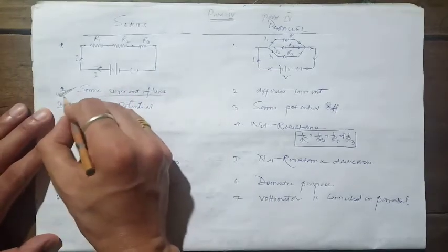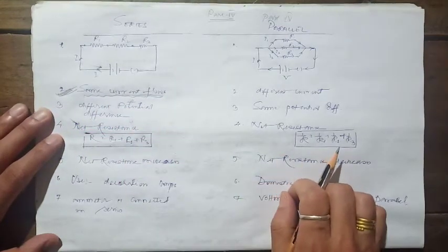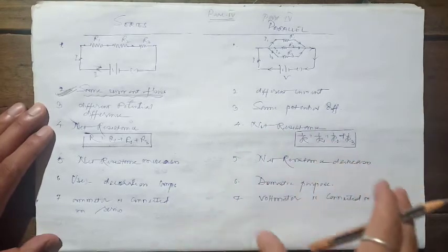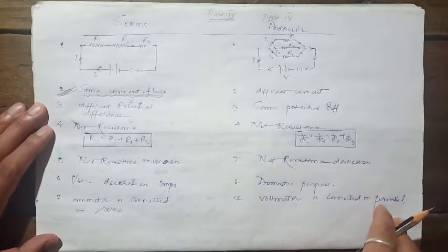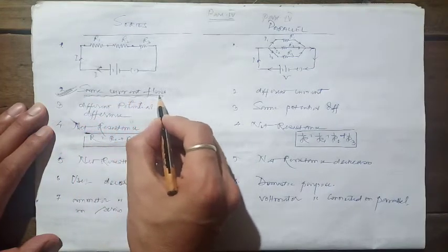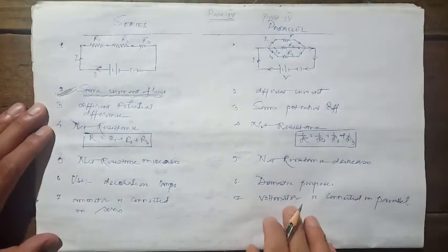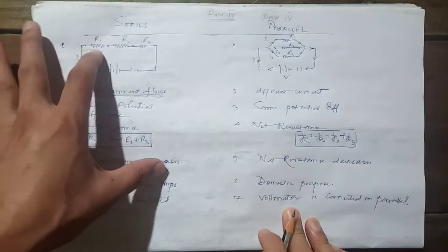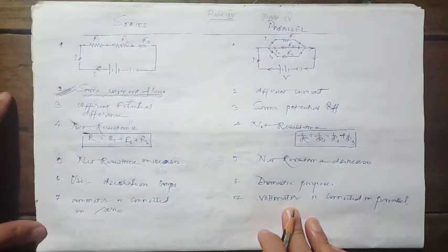And students, this point is very, very important. This point will help us identify how the resistors are connected, in series or in parallel. Sometimes in complex circuits, we have to identify whether the resistors are connected in series or in parallel. The only way to identify this is to check whether the same amount of current is flowing through all the resistors or not. So this is how we connect the resistors in series, students. The end-to-end connection of all the resistors is called a series connection.